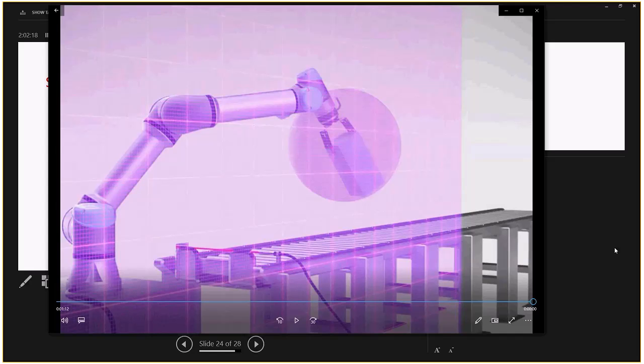And that's one thing. There's another thing that's going to activate if an operator puts more boxes than is supposed to be in there. Mind you, they don't work with the program. So the program is already set up so that whenever he grips, this is the amount of weight. It is normally 7 boxes, and those 7 boxes, I'm just saying, are 10 kilograms. If you got 10 boxes, it's over 10. That machine's going to stop right away. It's not going to go up.